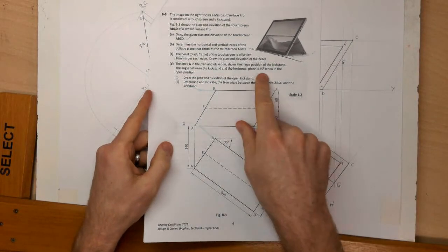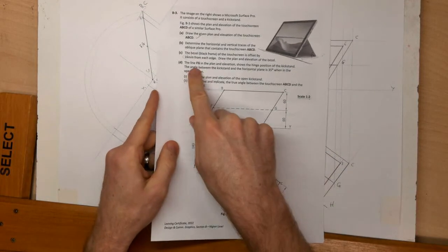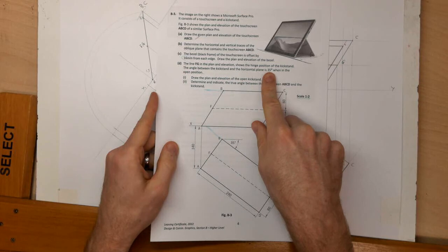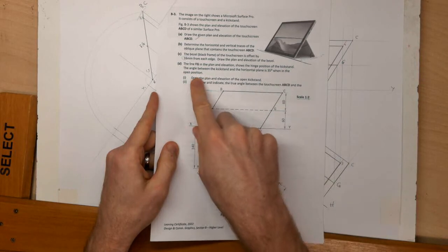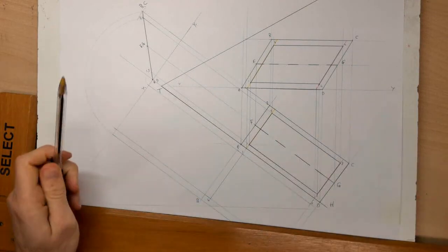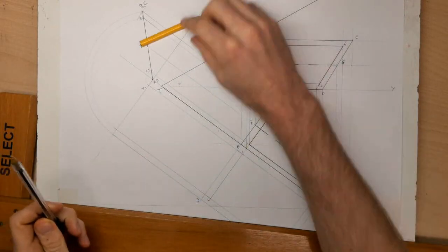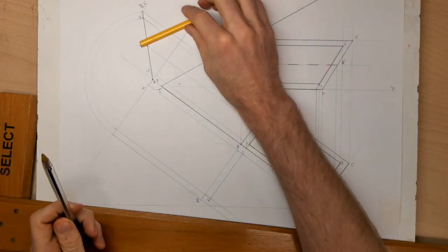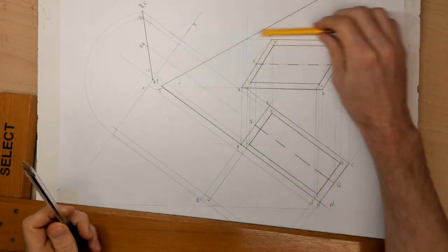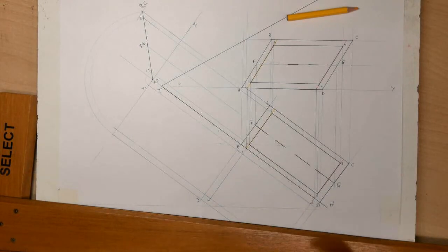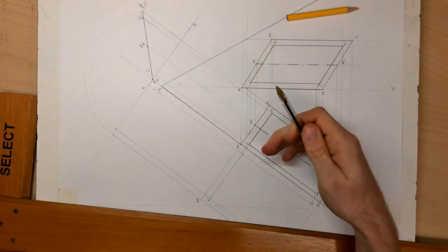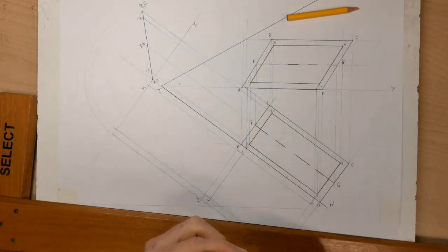So we have a point view of it now. The angle between the kickstand and the horizontal plane is 35 degrees in the open position. Okay, so our kickstand will be here at a 35 degree angle from FG to our horizontal plane. Because we're getting an edge view. Because we have a point view of FG, that gives us an edge view of that entire kickstand.